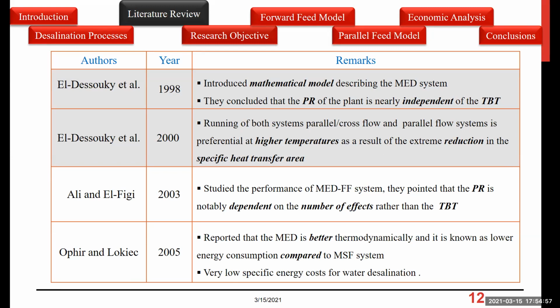And then in 1998, they introduced a mathematical model describing the MED system and gave a conclusion that PR is independent of the top brine temperature, which means that increasing or decreasing the top brine temperature does not really change the PR of the system, but the most influential part is the number of effects.